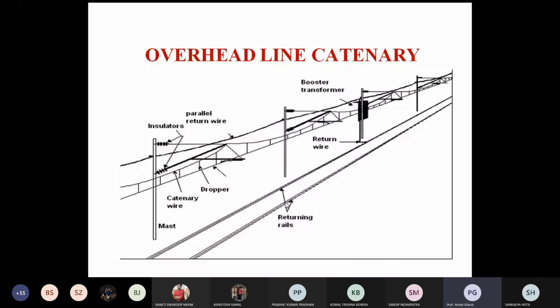You know that in our power plant generation, the ground is in the generating station. The ground is normally provided by a special type of transformer, with a zigzag transformer configuration. That type of transformer is called an earthing transformer, and the earthing is done with the earthing transformer. Why is it done in your generating station? Because the transformer directly earths the supply. And another return path is observed in the neutral.